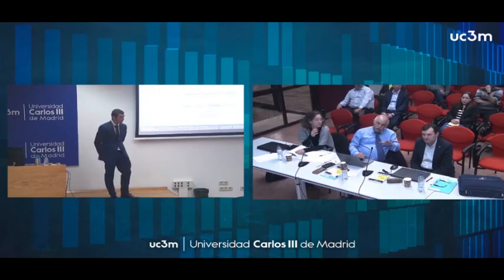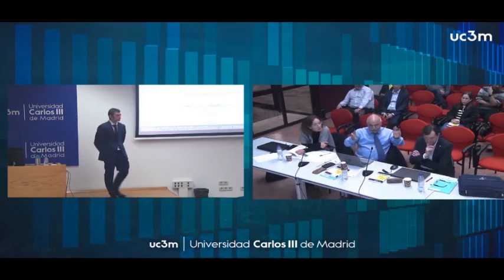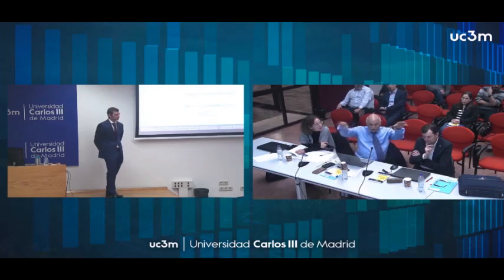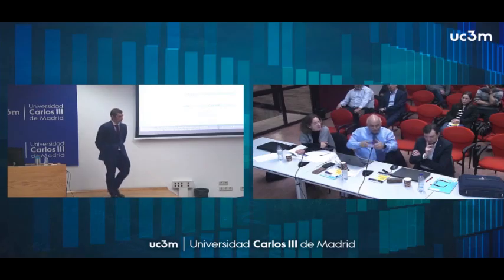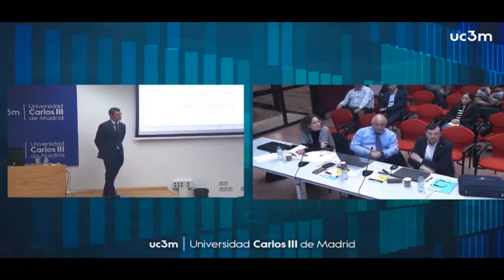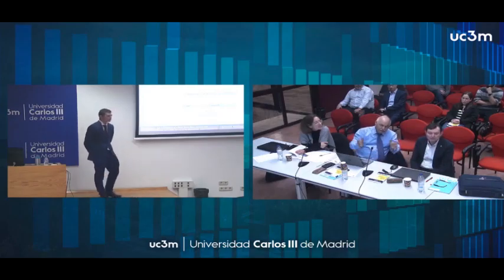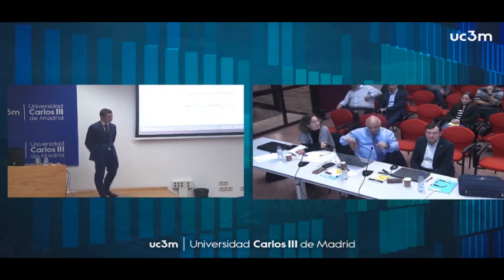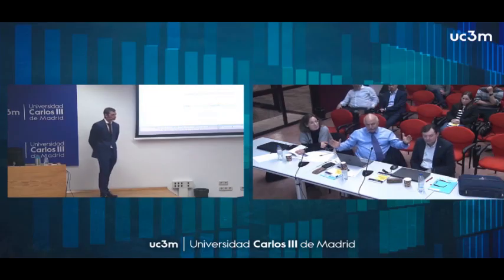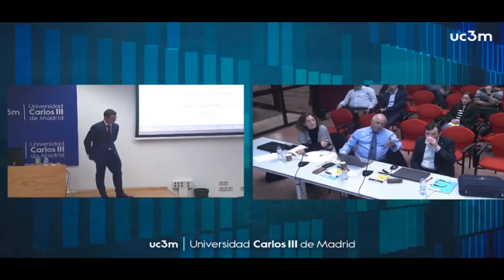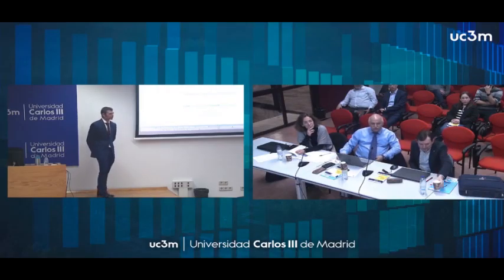Okay. Also, one suggestion I have concerning the base where you have the material to dry. Maybe there is a good idea to put some kind of lips, I would say, of parabolic shape, so any stray rays that may be reflected from somewhere else can be easily concentrated back to the base, like a third concentrator. Like a CPC concentrator, but not of a very big height, so as not to create problems to the other mirrors. But maybe a little bit, so as to have a slightly larger area, so as to get all those stray reflections that may happen in a real field. That could also be an interesting approach.